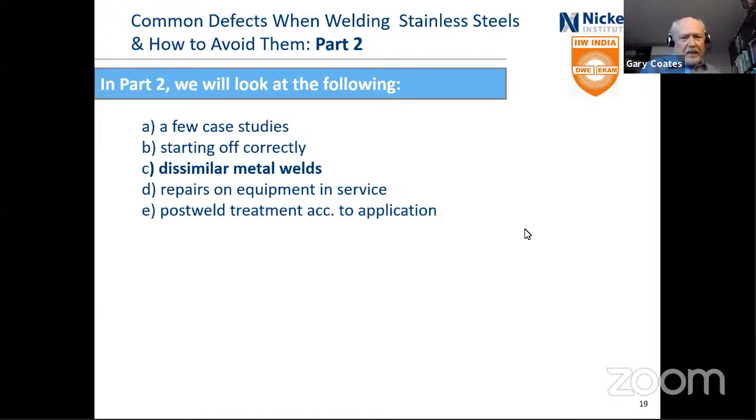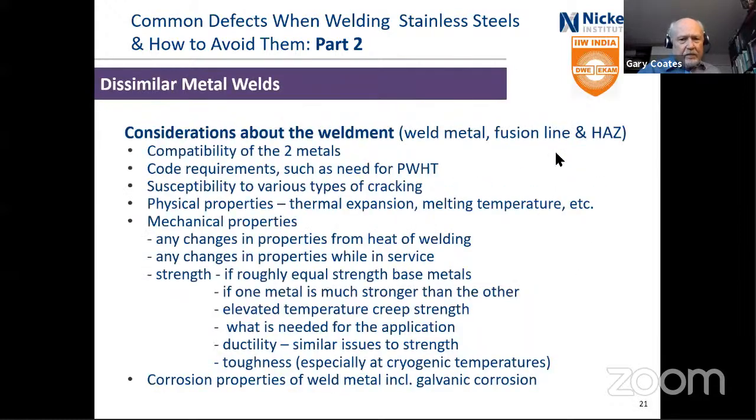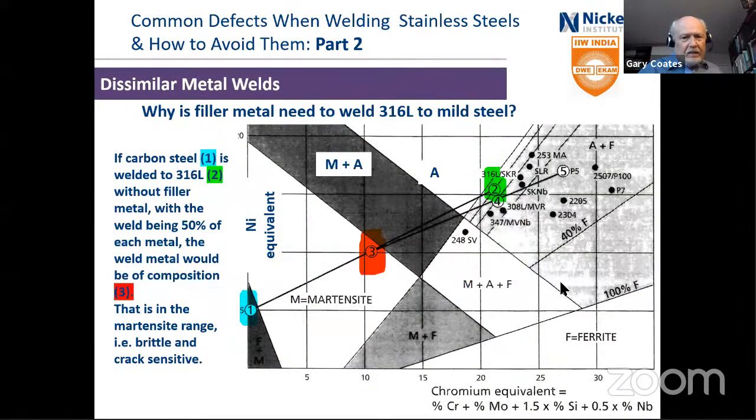Somebody was asking, I think in case 3, about the operating pressure. It was just a pipe that would flush out. They would open up a valve and the sewage would come out there. I'm not quite sure what the reason for it was, but there really was no pressure, but they would have to drain it. So you put the pipe at a slope so it does drain, but the important thing is to flush it out with water to make sure it is clean.